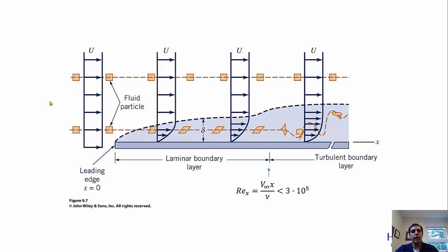And so what you wind up developing is what we call a boundary layer region, which I'll highlight here in red, where the height of this region where viscosity is dominating is given the symbol delta, and it increases with downstream distance. Now, the flow will start out laminar and then eventually, if the plate is long enough, transition into turbulence.